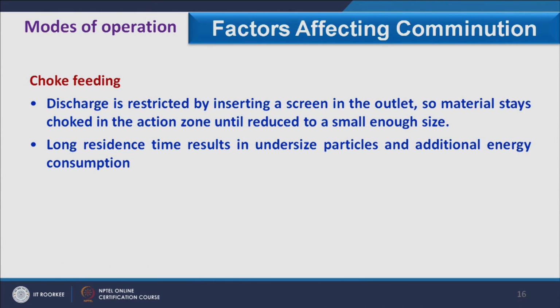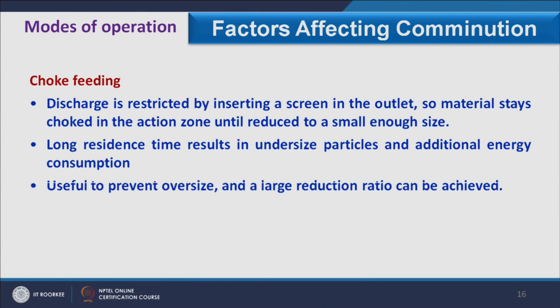So, the complete operation is carried out at choke condition. It has long residence time which results in undersized particles and additional energy consumption. Useful to prevent oversize, and a large reduction ratio can be achieved in this.